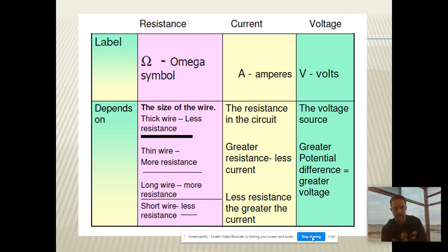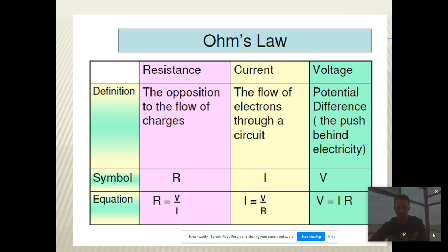And then for the last one there, where you've got 6 volts and 4 amps, the resistance there, let's see, current and voltage, this is always the weird one. Yeah, so you take your voltage divided by your current, so your resistance must be 1.5 there. Yeah, 1.5 ohms for your last one. Okay, now we'll actually stop and go look at a couple examples.